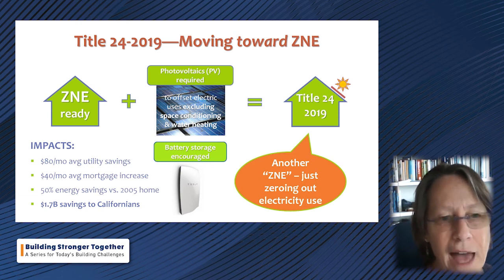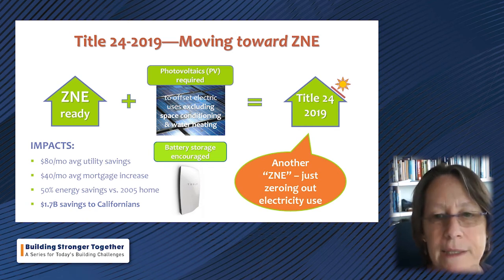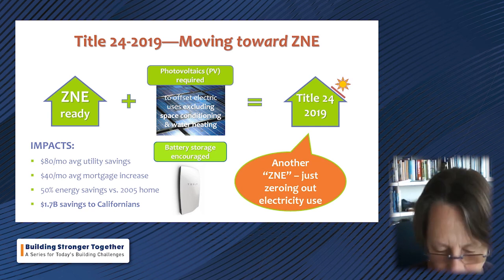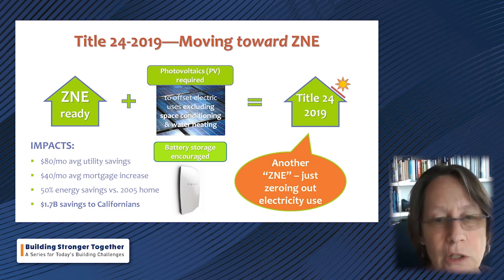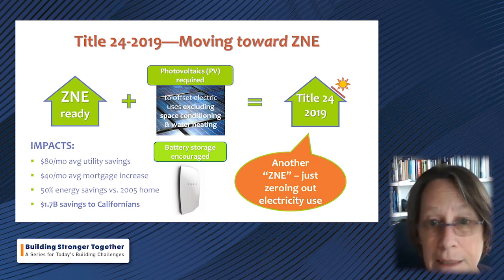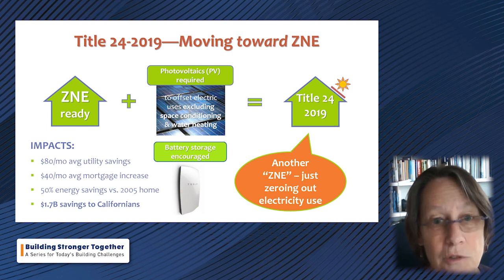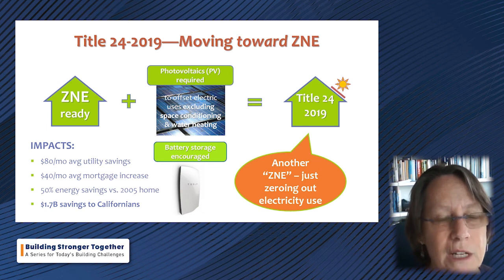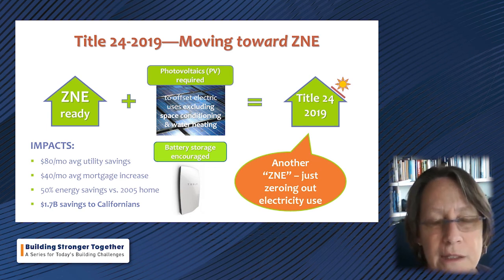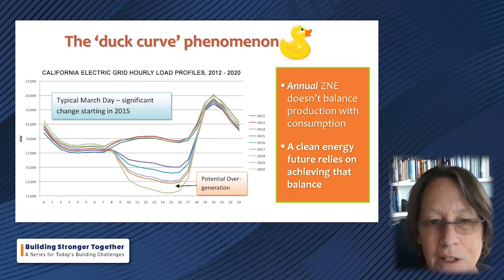And that is, again, assuming that the electric loads are the standard ones in a mixed fuel home. And this means there's not a different requirement whether the home is in fact all electric or mixed fuel. So we exclude the loads of water heating and space heating from that calculation to determine the size of the PV load.